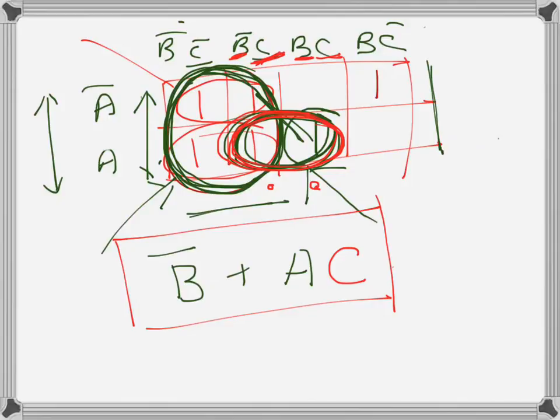And this is our minimized SOP expression from the K-map. I didn't draw the truth table, I just arbitrarily filled up the cells here just to show an example. But what we get from this example, if we had a truth table with 5 ones placed this way, the minimized sum of product expression we would get from the K-map is this one. I will do some more examples later, like I did before. So yeah, this is just the basic principle of grouping.